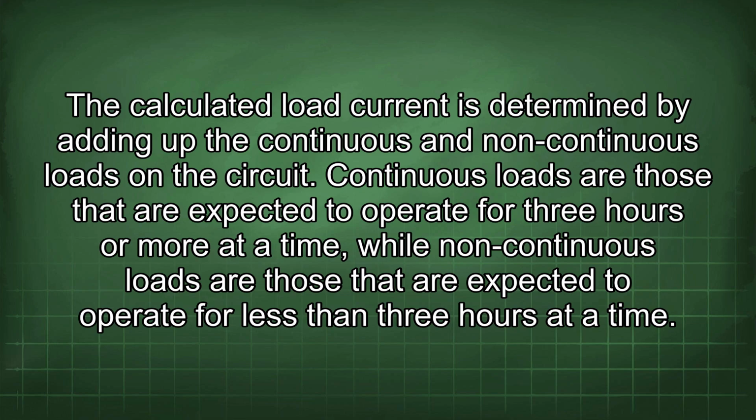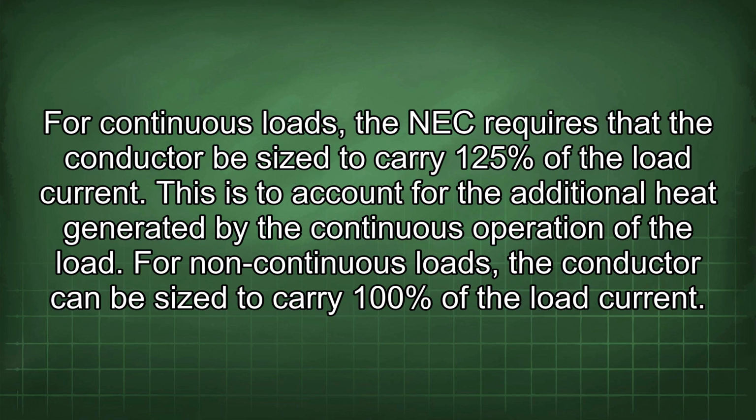Continuous loads are those that are expected to operate for 3 hours or more at a time, while non-continuous loads are those that are expected to operate for less than 3 hours at a time. For continuous loads, the NEC requires that the conductor be sized to carry 125% of the load current. This is to account for the additional heat generated by the continuous operation of the load. For non-continuous loads, the conductor can be sized to carry 100% of the load current.